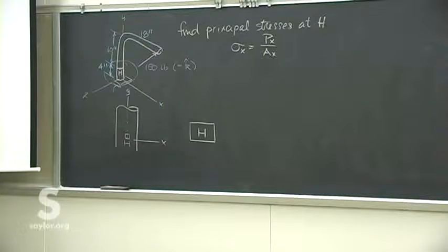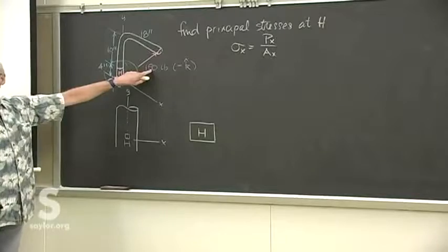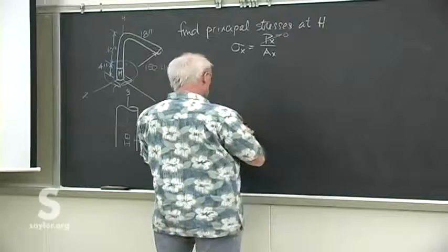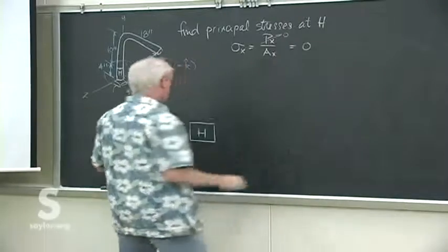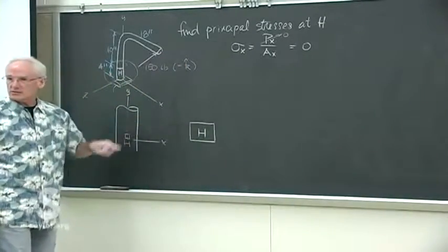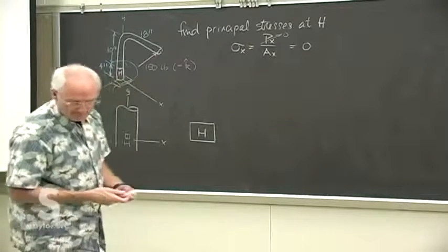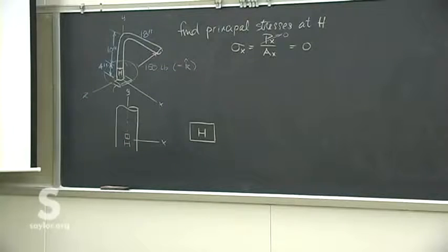Well, we don't have any forces in the X direction. We have a force in the Z direction, but not in the X direction. So that one's 0. So we have no X direction normal stress on that element H down the main shaft. And there's no bending in that X direction either.